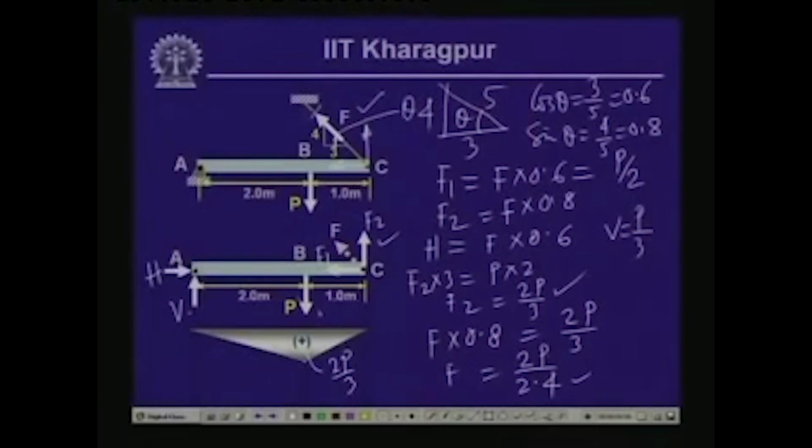So, you have the action of axial stress, which is normal stress, and because of bending you are going to get normal stress. Now, physically, because of this load P, at the top you will get compressive stress and at the bottom you will get tensile stress. Now, if we combine the compressive stresses because of the axial compression and the bending, we will get the maximum compressive stress, and if we limit that to 120, then we will get the value of the maximum stress.